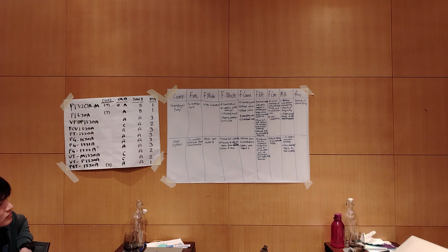In your FMEA, should you write your frequency or not? Yes. Should you put something like depends on failure frequency? You must have a specific value. Take review of vibration monitoring: the more frequently you do your vibration monitoring, will it impact your high vibration or not?